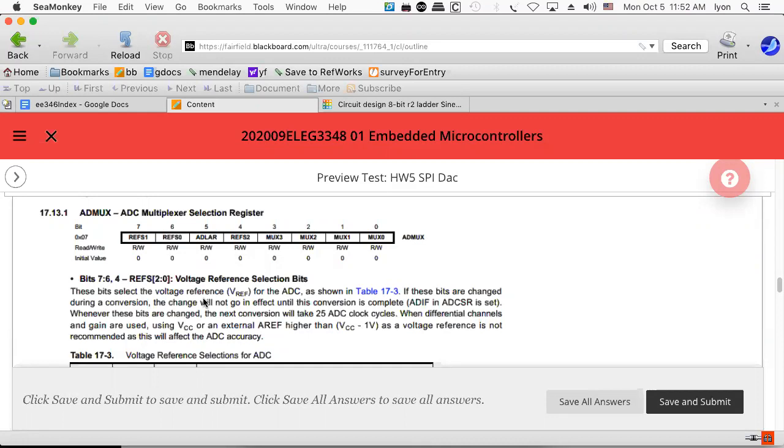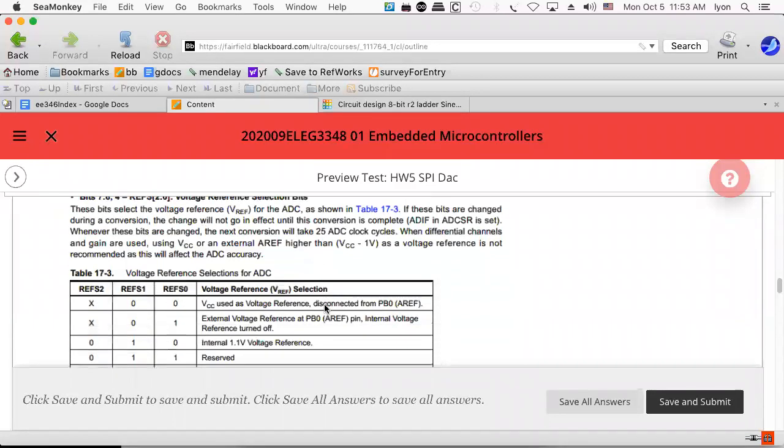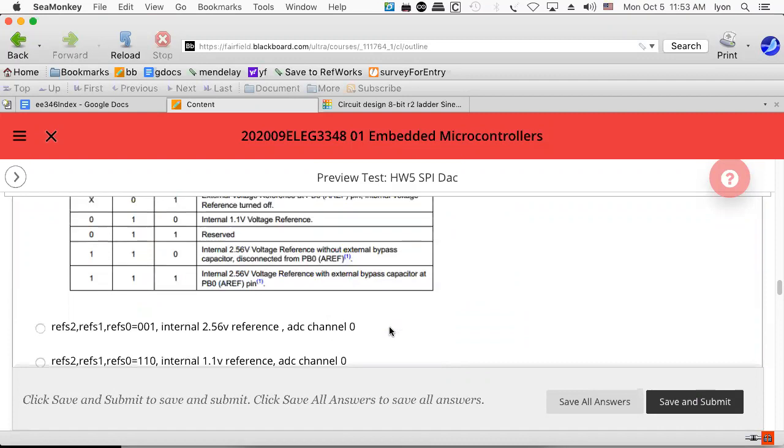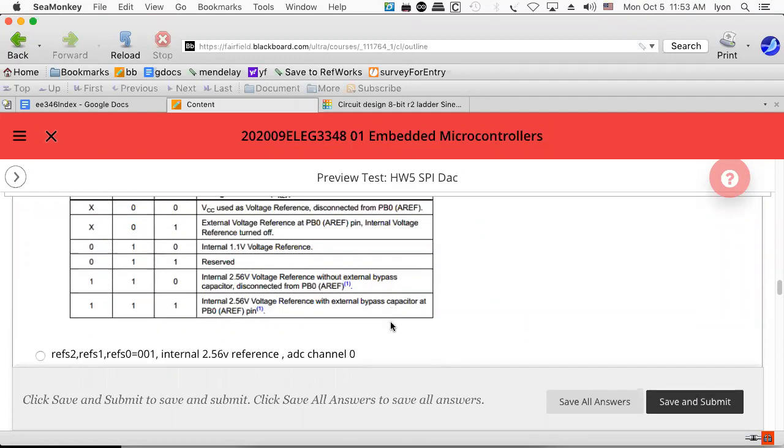That's like a real electrical engineering kind of consideration because guitars don't output 0 to 5 volts. The real world is not 0 to 5 volts. It's just not. And so you have to consider whether or not you want to use an external voltage reference or the internal voltage reference. And so we've got a nice internal voltage reference, which saves us a whole pile of work.